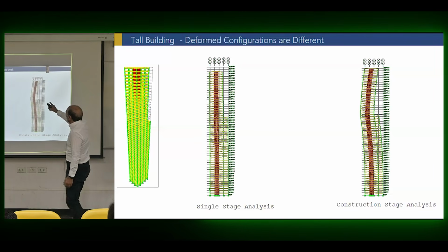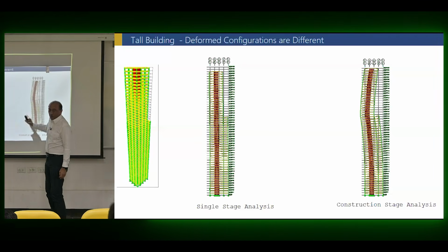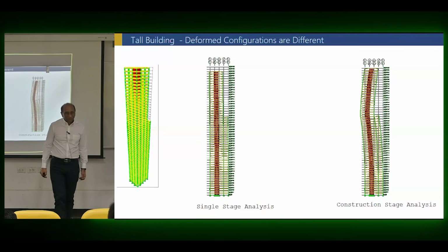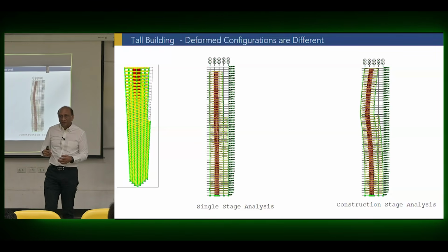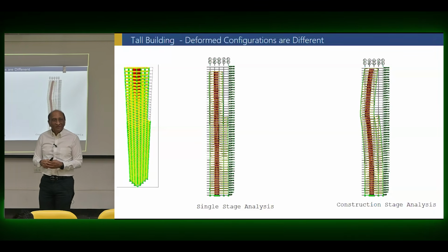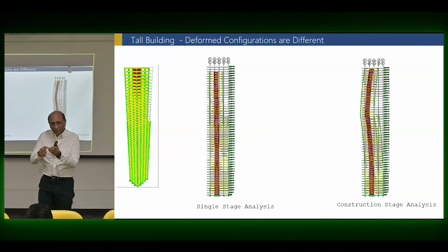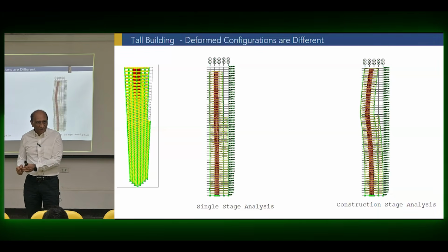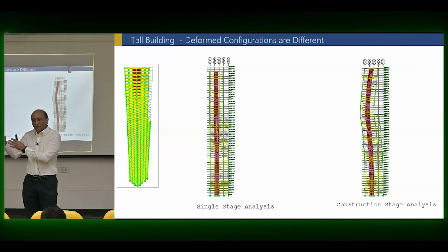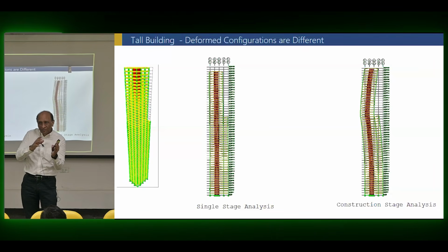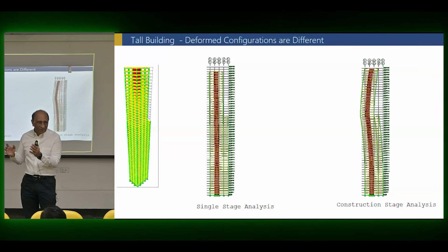So the last floor is still aligned, but previous floors, they have no control. It went on. Some buildings in Dubai and other places, which are so highly unsymmetrical that they post-tension them later. So gradually, they keep post-tensioning the columns or walls or system to try to keep bringing it back.